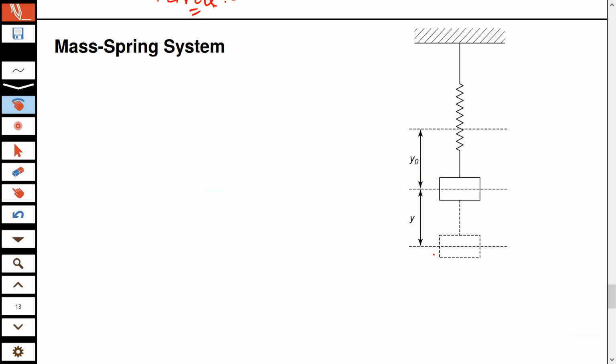Acha, here you have another example, and this is a vertical mass spring, and let's say this is its rest position. यहाँ से स्टार्ट करता है, ठीक है? तो इस जगह पे even if it is not moving, इसका जो बैलेंस अगर हम लिखना चाहते हैं तो the gravity mg, जैसे अगर इसका मास m है, must be balanced by the restoring force k times y naught.